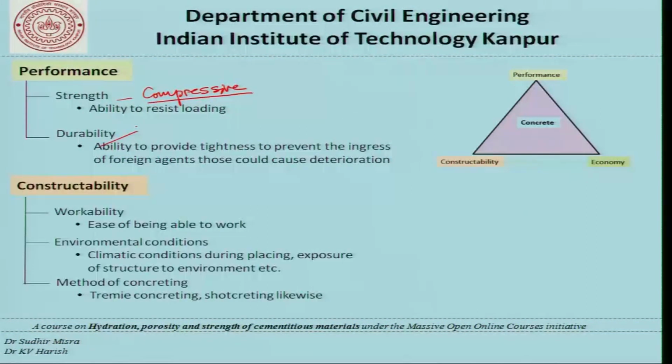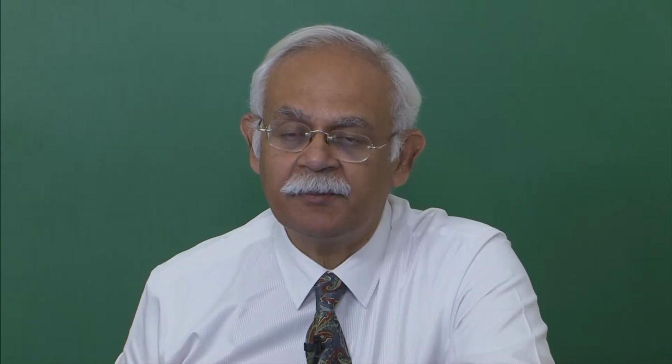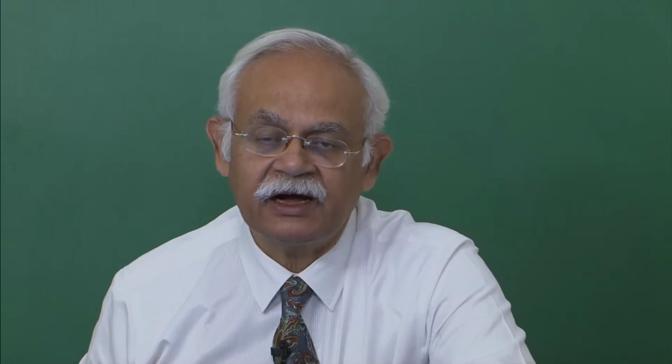Now, when it comes to constructability, the ease with which the construction can be carried out, we have to see the workability of the concrete, that is the ease with which it can be worked in fresh state to different shapes and sizes without segregating, that is without the coarse aggregate being separated from mortar, without the paste being separated from the sand, and without the water appearing on the top as if the other materials have been allowed to settle down.